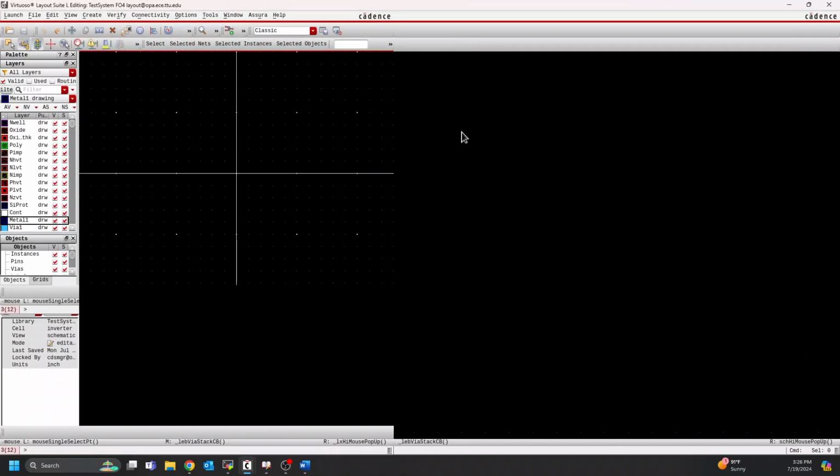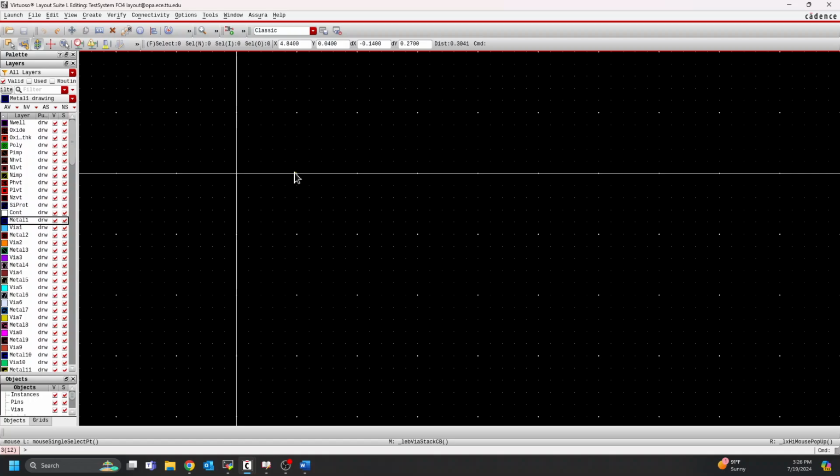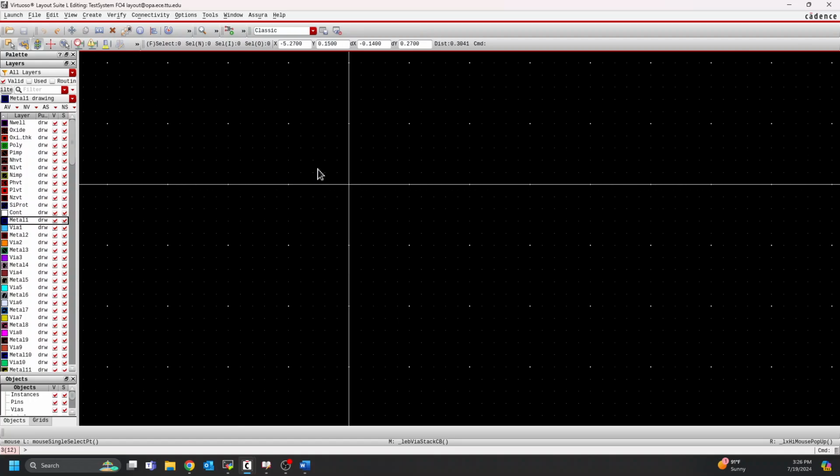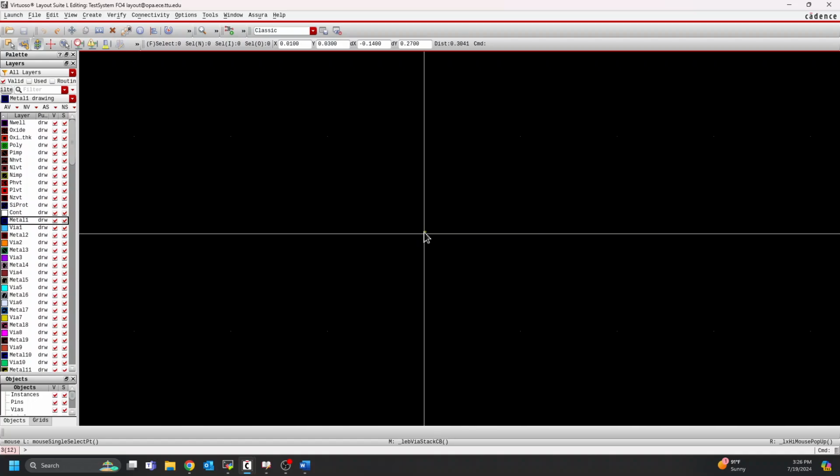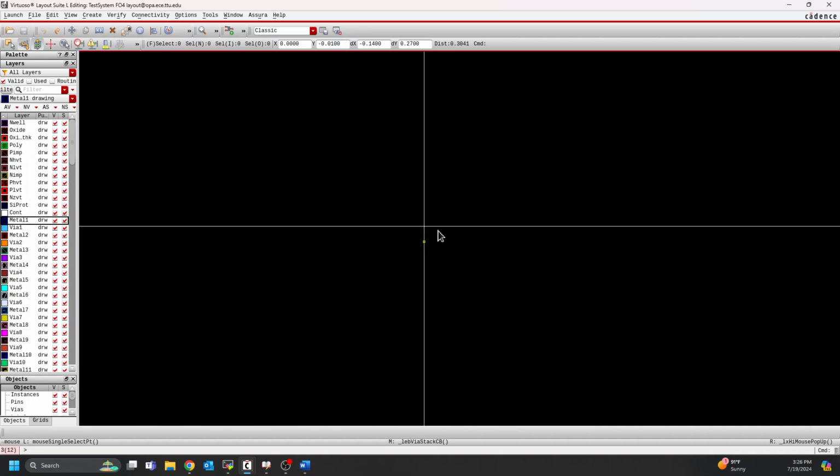And in this case, for a fan-out 4, we have 1 input inverter. The output is split to 4 different inverters, and then those outputs can be connected together, or they can be separate, things like that. But what we can do here is kind of like how we did it in our schematic. Instead of having to replace every single transistor, so for fan-out 4, it could be 10 total transistors. Of course, that doesn't seem too complex, but if you have something more complex like an ALU or CPU, then that can become very cumbersome. But what we can do here is actually use layout blocks that we've generated previously.